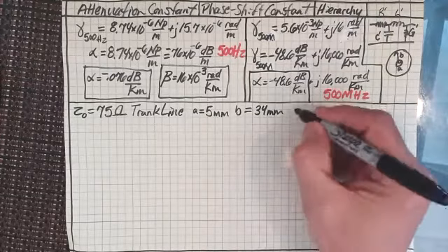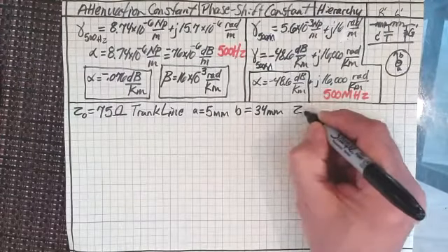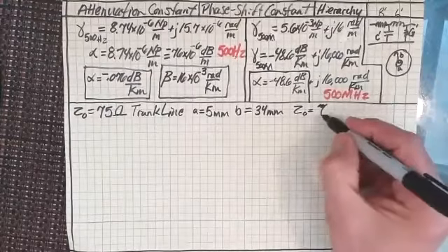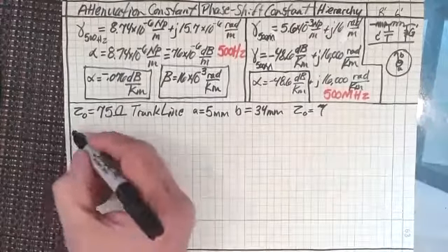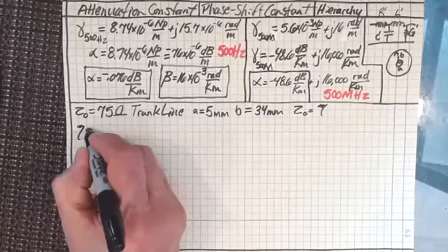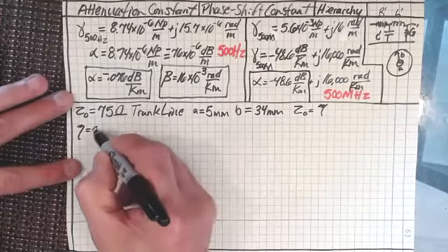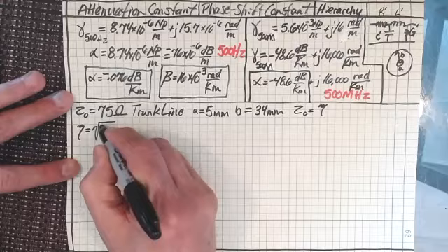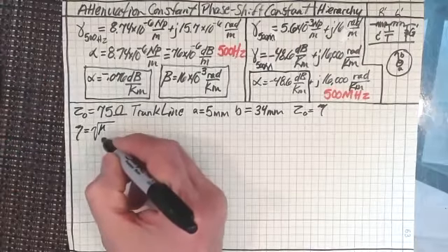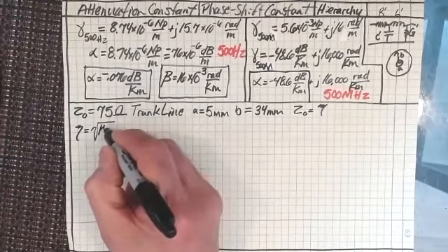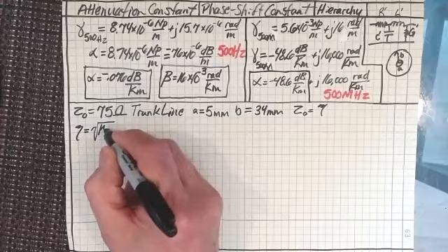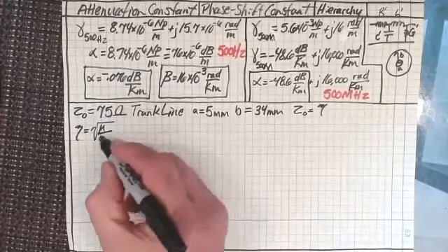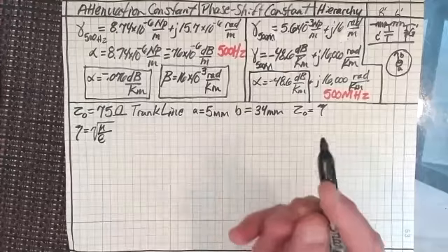Because we know that the characteristic impedance is eta, and again, I'll write down what eta is. Eta is always the square root of the permeability of the dielectric, over epsilon of the dielectric.